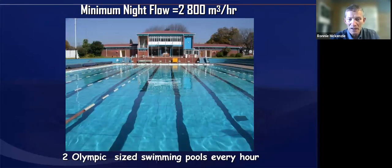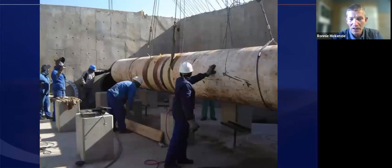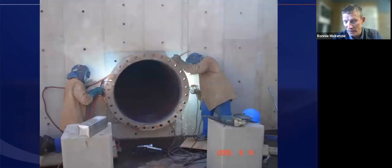The minimum night flow was originally 2,800 cubes an hour, which is one of the highest minimum night flows that we've seen. And we managed to build this using labor-based construction, which means that everything was hand dug. So you dig it out with picks and shovels, the old way. Cut into the big pipe. That's us cutting into the pipe. That's us welding on a big flange plate.